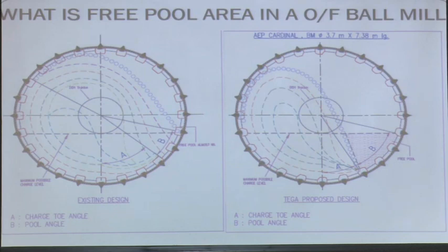Now, in one of the plants in Africa, it so happened they wanted to push more, right? And that mill was operating in a closed circuit. What happened? In that method, they just forgot to maintain the desired percent solids in the mill. So, the percent solids in the mill was in the tune of 74 for a gold or ball milling, right? 74% solids. And because of that, the rheology got changed, rheology impaired the grinding. So, they started first generating the coarse.